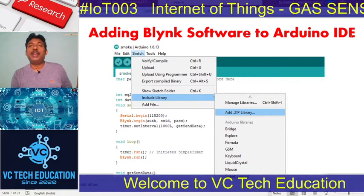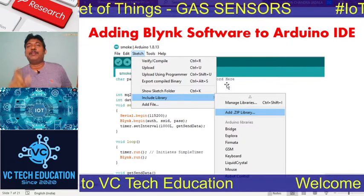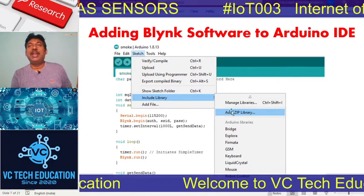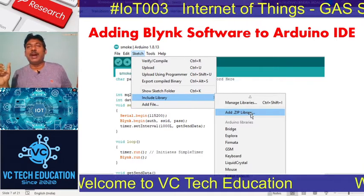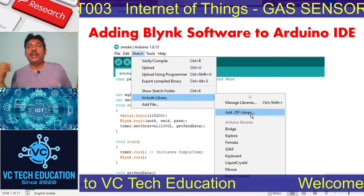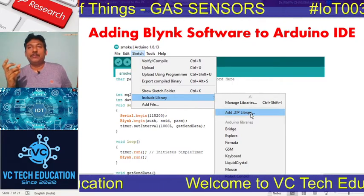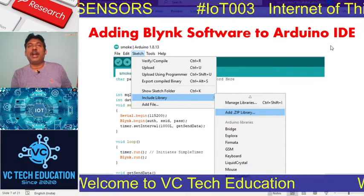From the Arduino IDE, you have to add that particular zip library. So go to Sketch, then Include Library, Add .ZIP Library. By clicking it, it will give us the path. You have to set that and upload that zip bundle of the library to this particular Arduino IDE.